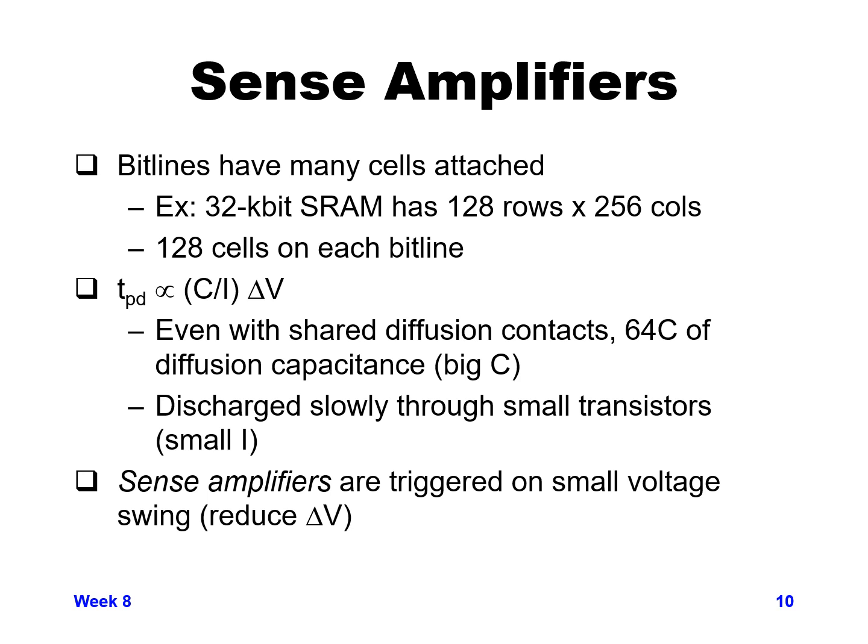Keep in mind it's being discharged through really small transistors, because we're trying to make these transistors as small as possible to have our array size as small as possible. This means a very small current on a very large capacitance. It's going to be a really large delay if we need to get it discharged all the way from VDD to ground.